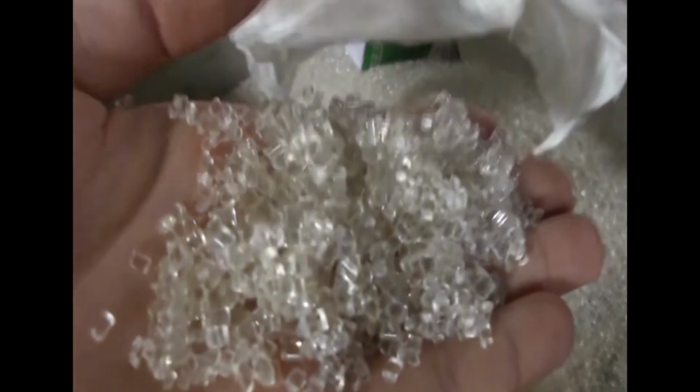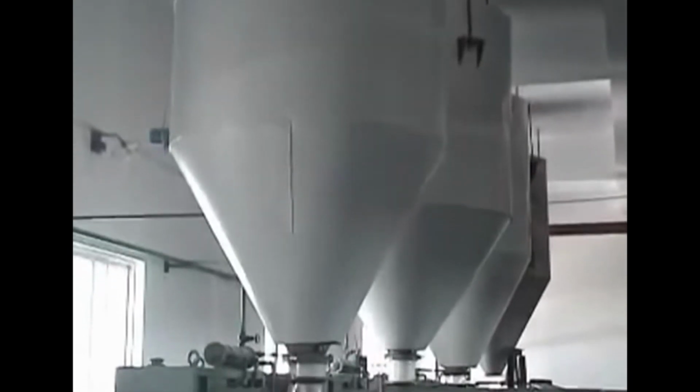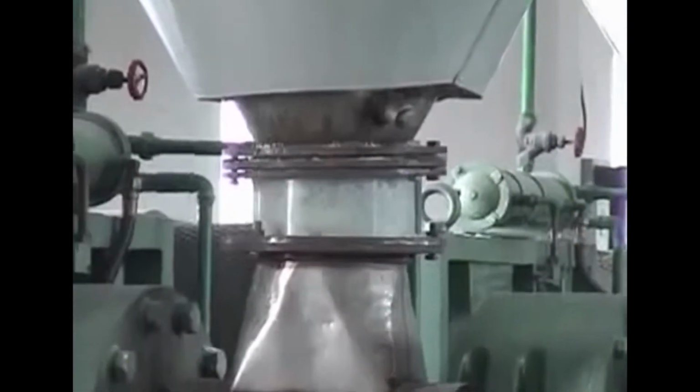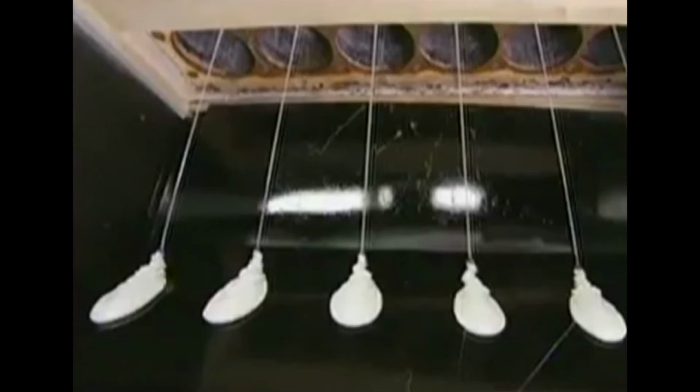In this, first polymer chips come from the chemical factory, and they are placed in a hopper. Several chips from different machines will be brought in and put through a hopper, and then they will get mixed to get a uniform polymer, and then they are made to fall on a hot grid. When it falls on the hot grid, it melts, and the molten solution is then collected and filtered in order to remove any suspended impurities which will interfere with the holes of the spinneret. They may block the holes of the spinneret and stop the formation of the filament.